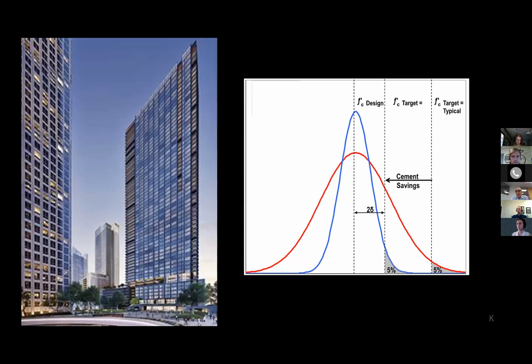And in that sync, the first mixes that came to us, actually none of them used the imported aggregates of the Polaris rock coming from British Columbia. Using the local rock supply, because of its inconsistency, is one of the reasons the cement content is so high in a lot of mixes in LA. That higher cement content is how they manage that inconsistency in the rock.